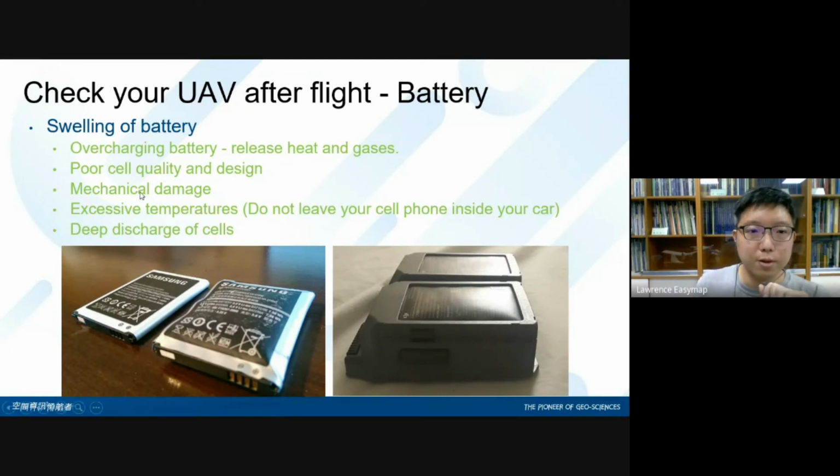And of course, if the battery itself is of poor quality or poor design, the effect may be more significant. Some mechanical damage, maybe it was dropped on the ground, or some heating from other objects, will make the battery swell as well. And sometimes deep discharge of the cell or excessive temperature. So therefore, never place your lithium battery under very hot temperature or inside your car during the summertime. It is very dangerous.